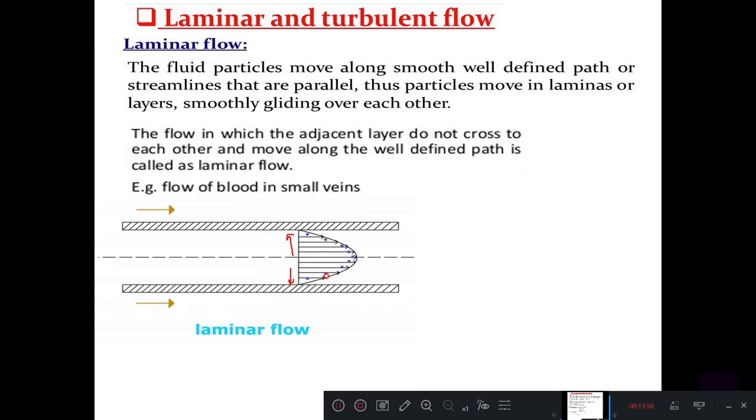Laminar flow generally happens when dealing with small pipes, low flow velocities, and highly viscous fluids. At low velocities, fluids tend to flow without lateral mixing, and adjacent layers slide past one another like playing cards. So there are neither cross currents nor eddies in laminar flow.